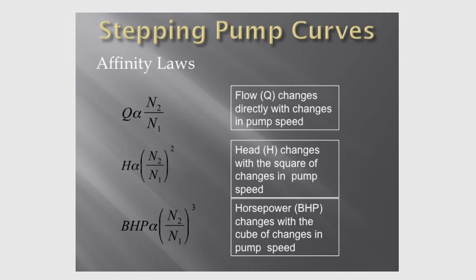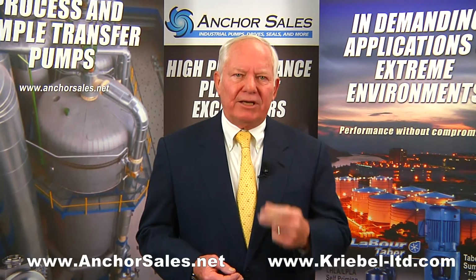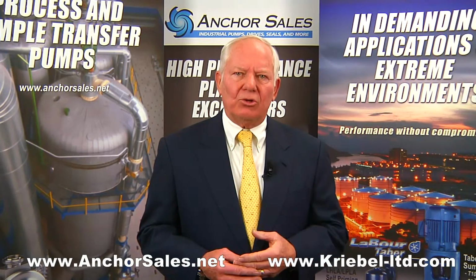The flow change is directly proportional to the change in speed. The head changes as the square of the change in speed, and the horsepower changes as the cube of the change in speed. With the advent of variable speed drives, this relationship is used a lot for pump control. Let's look at two applications to illustrate these laws.